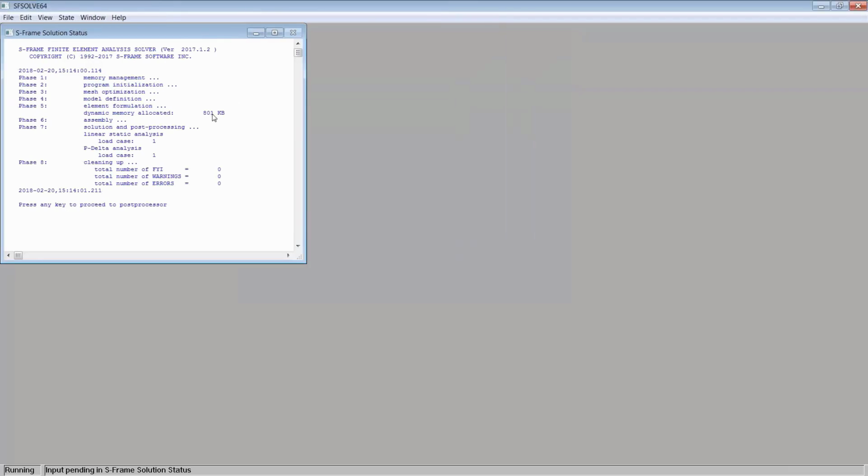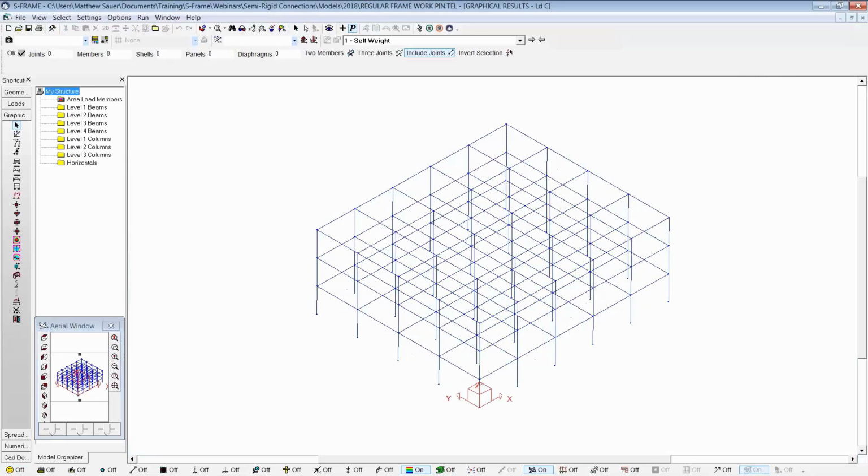And if I drag my solution trail over, you can see that we're getting a clean solution this time, which is exactly what we want. And if nothing else, even if we didn't want our connections between our beams and columns to be partially released, and we didn't want moment in our columns, this tool still allows me to quickly isolate where this instability might have occurred. And it was pretty clear to me there that the instability had something to do with my moment releases, and something might need to be done.